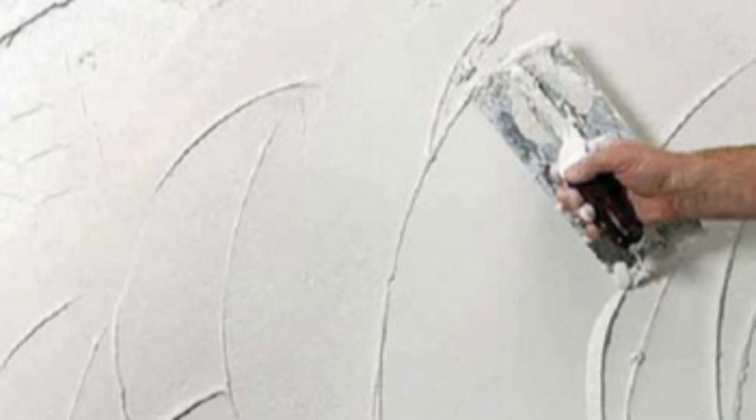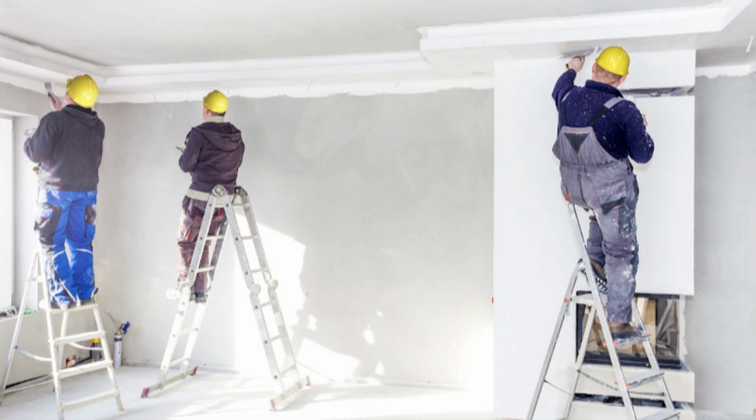It is a non-combustible material, so it acts as a fire resistance, which makes it a good choice for fireproofing walls and ceilings. In gypsum plastering, there will not be any shrinkage cracks. The gypsum reaction produces less heat as compared to the cement reaction with water. So there are fewer shrinkage cracks in gypsum plaster as compared to traditional cement mortar plaster.